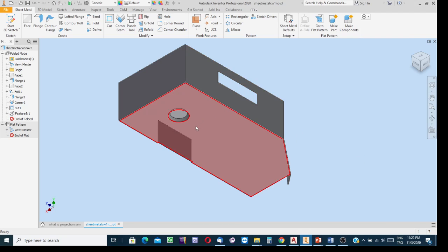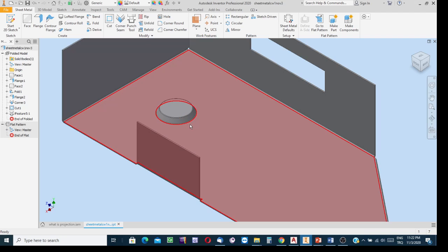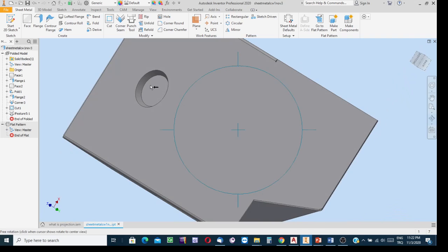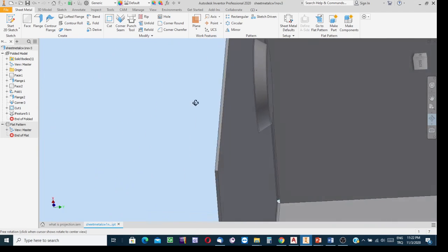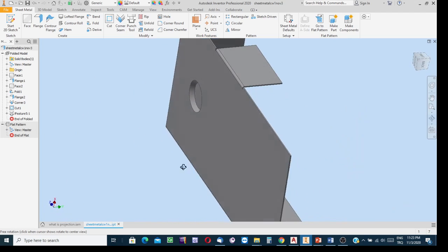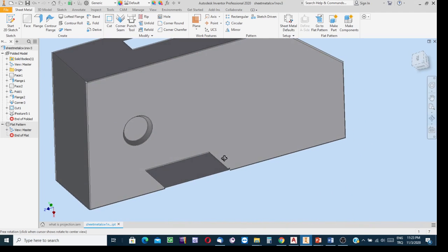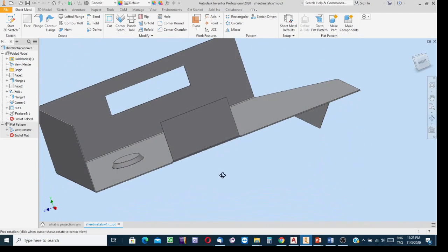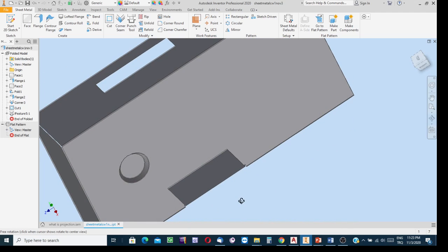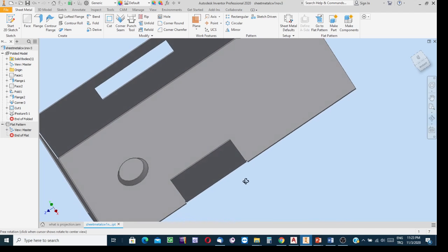You see, if you mark the center of the flat surface of the emboss at this side, then embossing will be in that direction. Okay, and see the other side. At the other side, you see we have a blind cavity. One side it is embossed, but at this side we have such an empty space. Deep drawing process. The cavity will be at the opposite side of the surface on which we mark the centroid of the emboss.